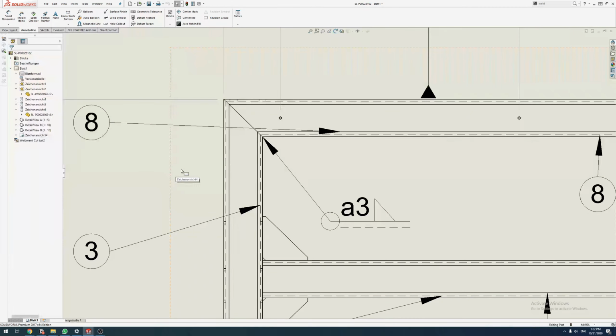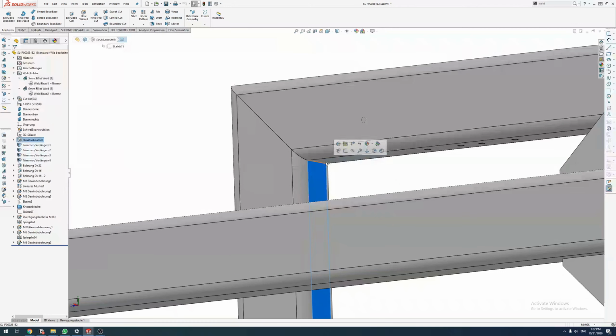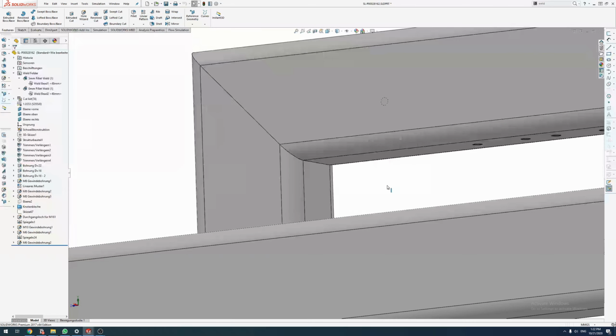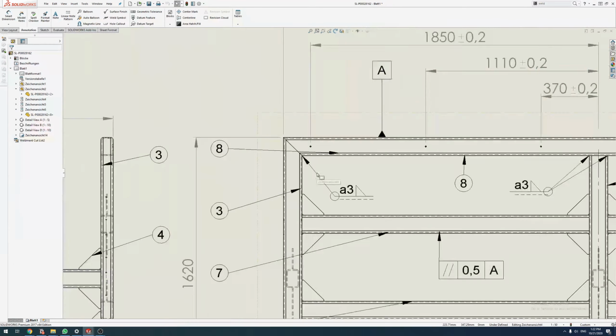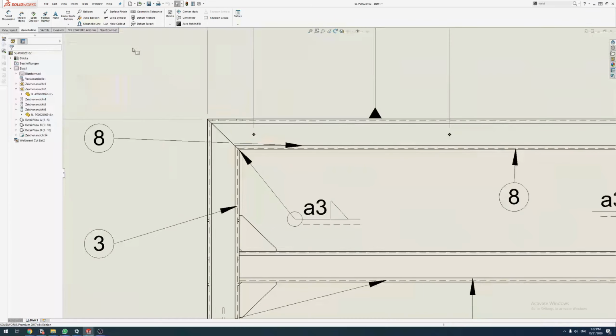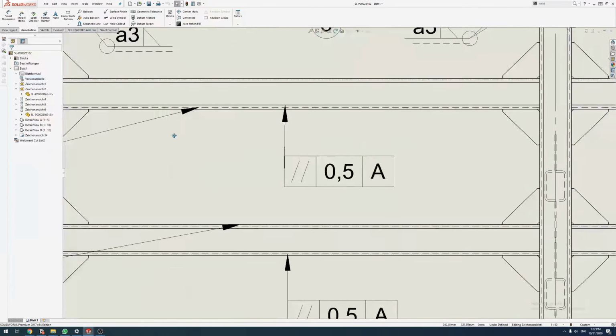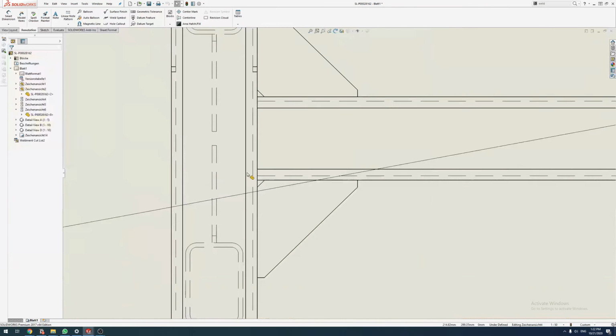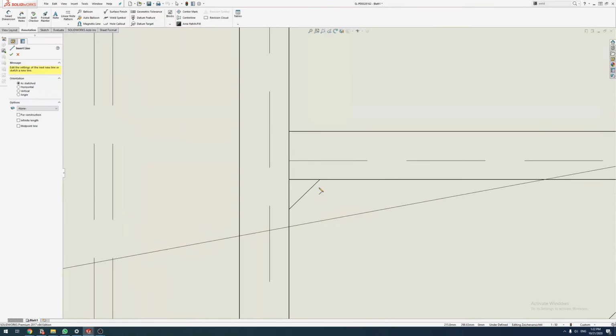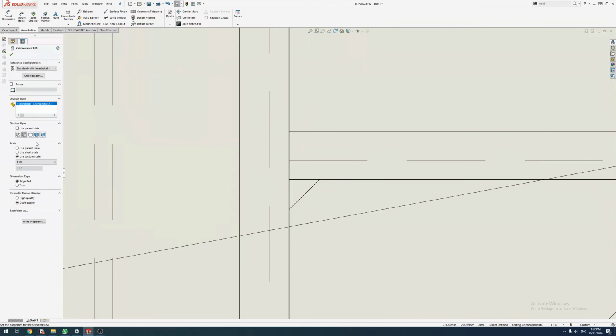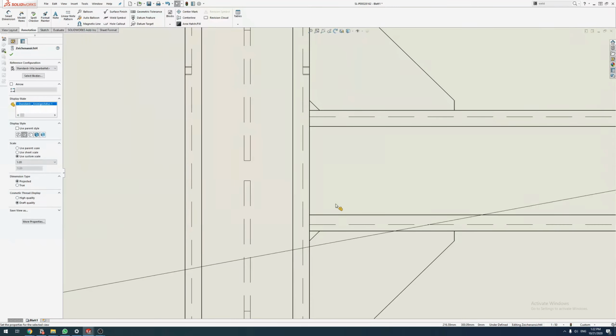In Solid Edge, you can define a seam like this. It will also generate a geometry and weld symbol so that you can go to the drawing. You can select this, and you will have a little rectangle, right? It will be black in the middle, and you can call it out.